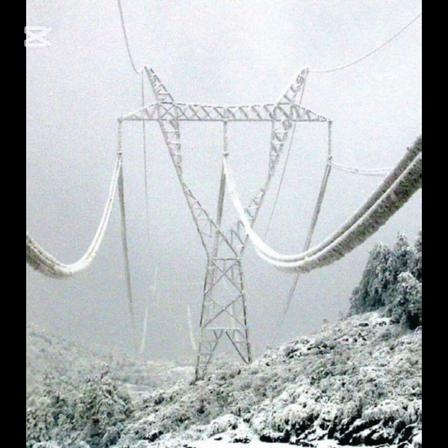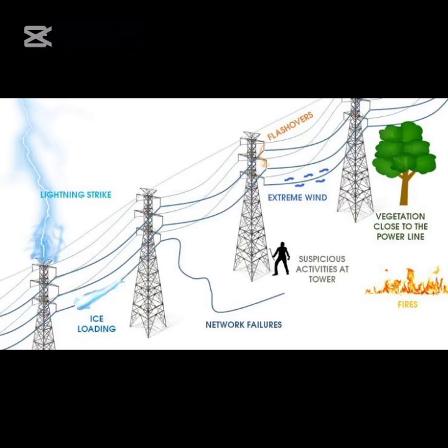2. Increased mechanical stress. Wind forces, particularly during strong storms, exert pressure on conductors, which combined with ice increases stress on the conductors, poles, and towers. This can jeopardize the structural integrity of the power line components. 3. Sag and tension variations. The presence of ice and wind can modify the sag and tension of conductors, leading to possible conductor breakage if the tension surpasses safe limits.